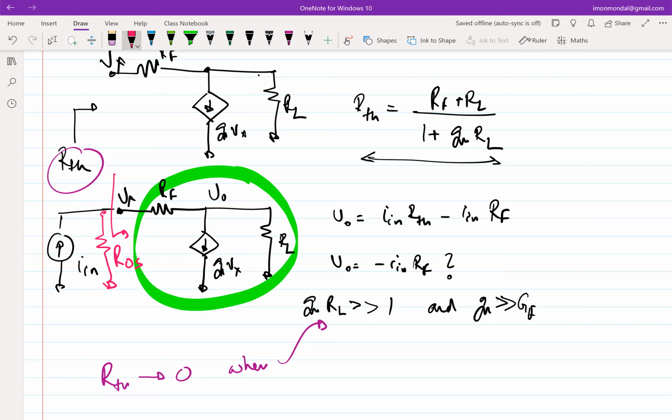Now, when you are designing, this source will not be a current source as is. It might be another block that is driving this block, and that block might have an output stage which behaves like a current source. It should not surprise you at this point, because a transistor essentially is a voltage controlled current source, right?